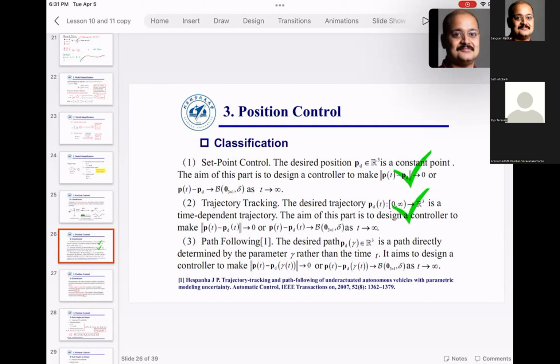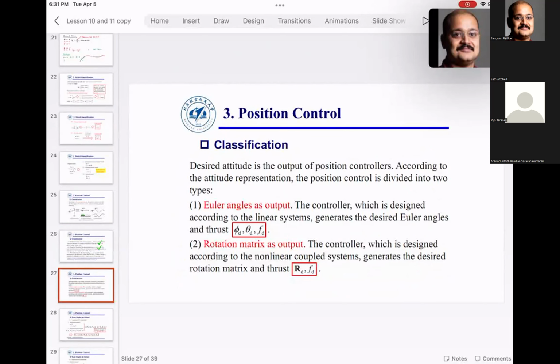And then you want to make sure that at every time, the position obtained from that path equation and the position actually reached by the quadcopter are within some norm. It's not the difference at one point, it's not the difference at a few points, it's the cumulative error over all the points. So that is what is meant by the error in path following.